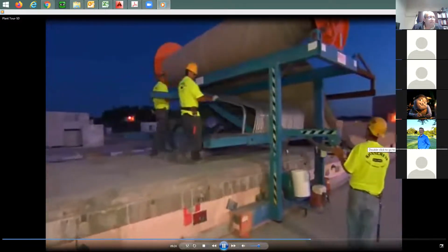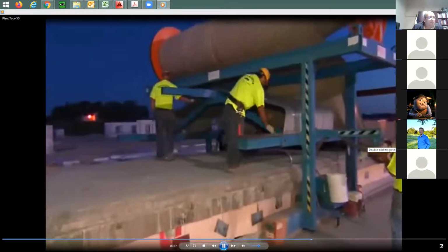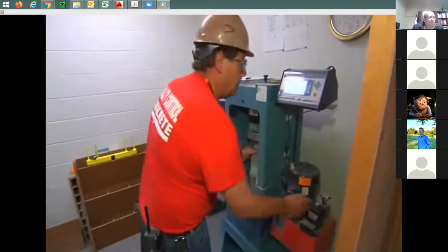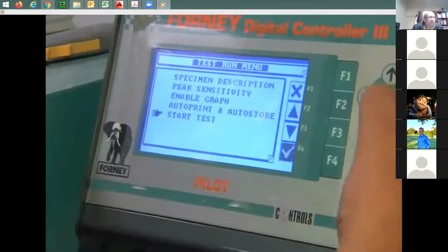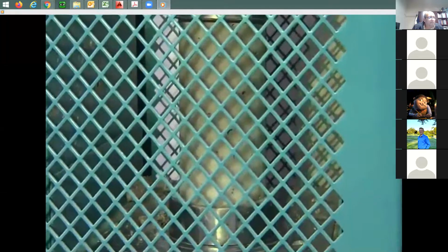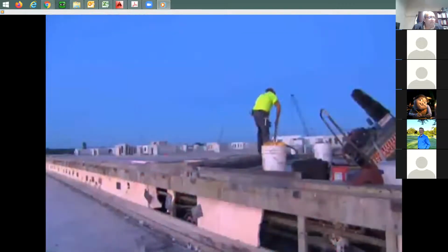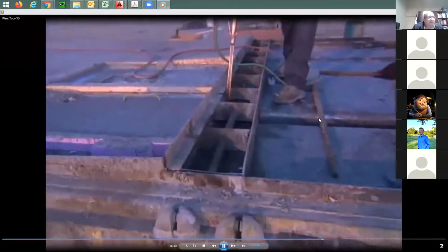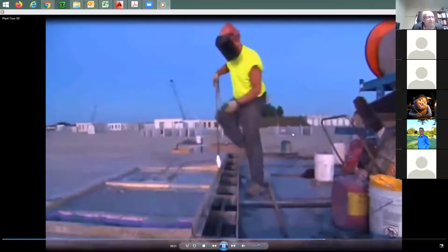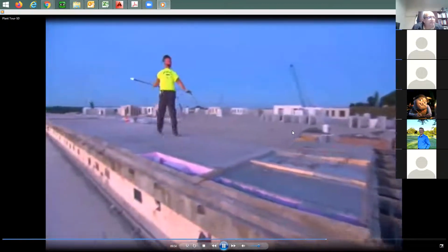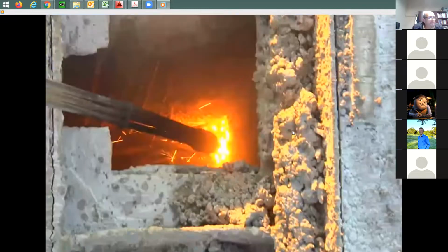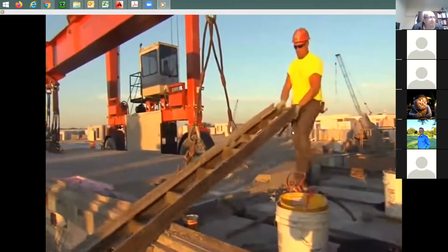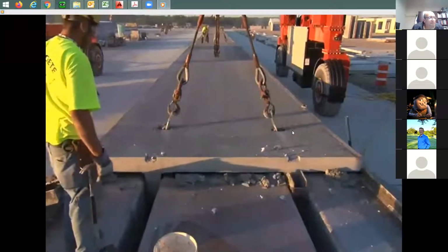After 12 to 16 hours of curing, the T's are ready to be stripped. The QC department first tests the concrete to be sure it has achieved the strength required to detension the strands, typically 3,500 psi. This is a typical test being conducted. The strands are detensioned in a specific sequence established by the QC department or the plant engineer. At the bottom, here, personnel are positioned at each end of the bed and at some of the intermediate bulkhead locations. On a signal, they burn the strand at each end. After all the strands are cut and block-out formwork has been removed, the T's are stripped from the form.